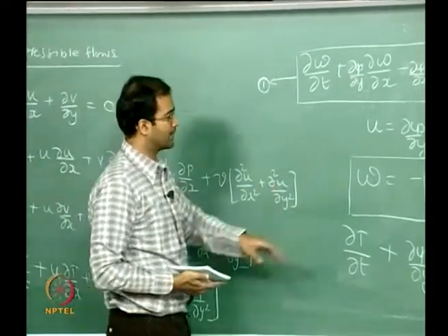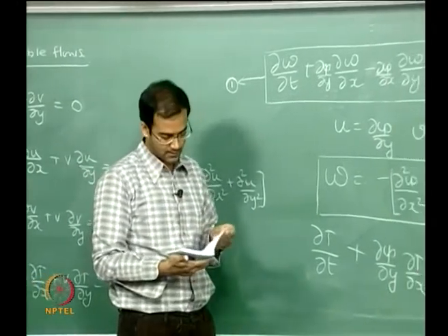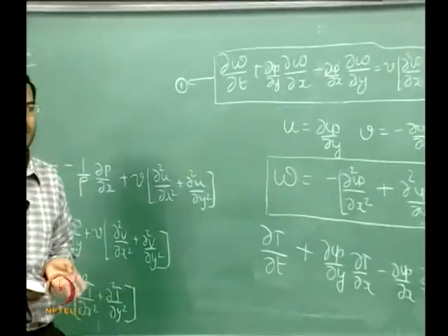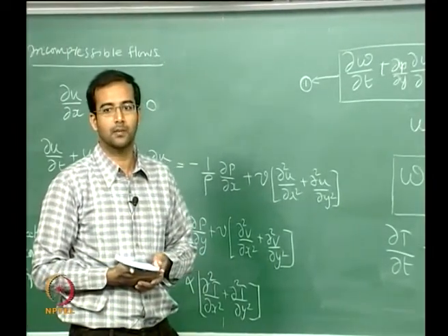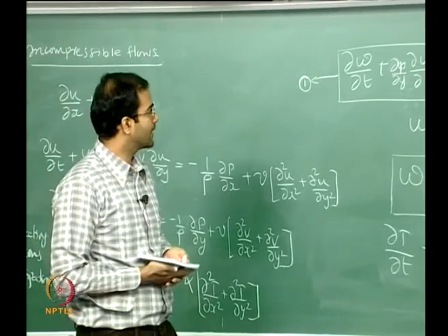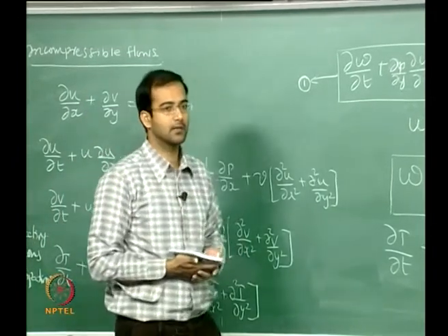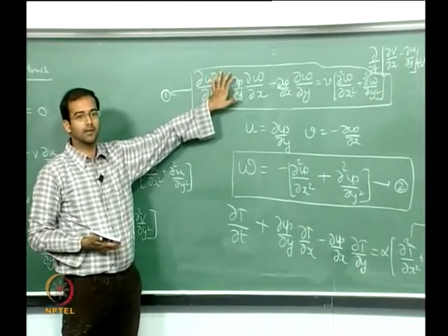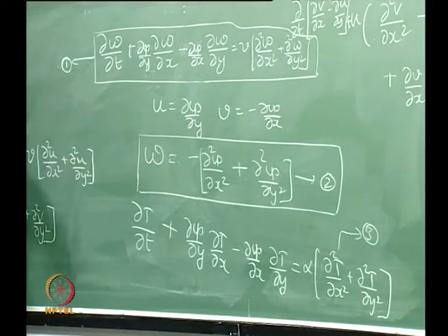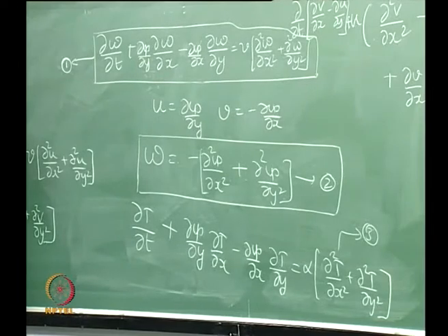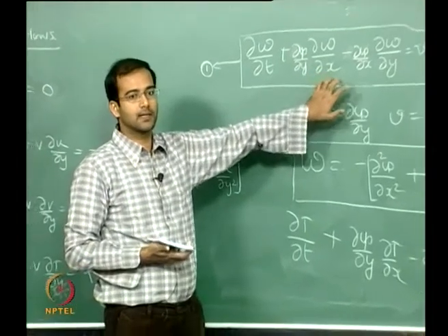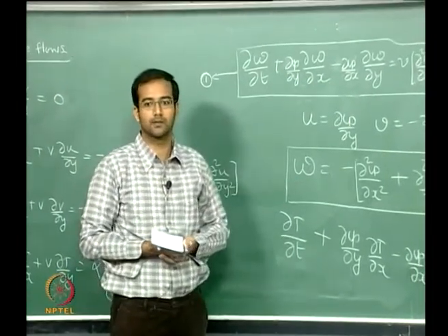So these are the equations that you exactly have to solve in your particular project, and I will be giving the papers. You have to apply the corresponding boundary conditions to solve this problem. For a particular problem you can look at the steady state solution, where you don't have to consider the time derivative, only the spatial derivative, and you can do this iteratively. There are a couple of techniques like Gauss-Seidel or Gauss-Jacobi iterative techniques, and you can use simple finite differences to discretize these derivative terms.